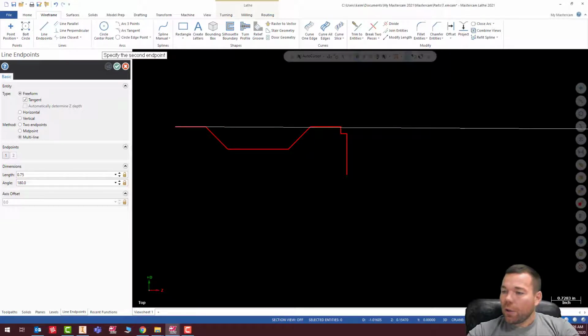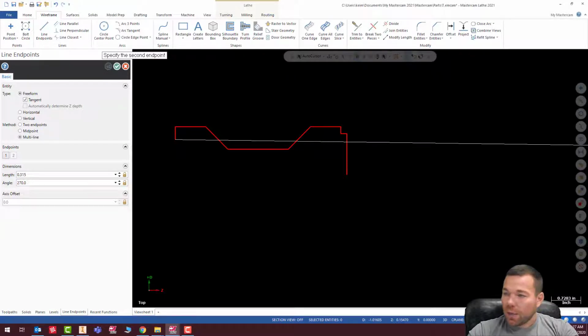And for that lobed shape on the back side, it's saying the maximum diameter is 1.7, so I'm going to make that a little bigger, maybe about 10 or 20 thousandths bigger, just so that I'm cutting something off when I machine that with the end mill. So I'm going to take this down to 1.72, negative 4.25, and then 1.72, negative 4.5, and that should be good.